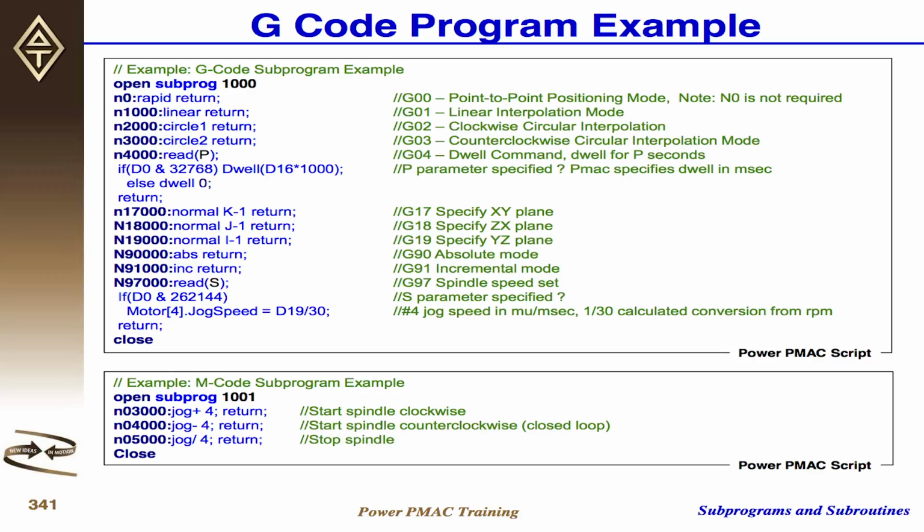So now you're checking the D0, this is the whole register, and the 2 to the 15 of the bit, which is 32,768, right? 2 to the 15. If you check this in the if statement, you're going to see if that bit is high or not. If the bit is high, you have successfully read it. So that's why you want to check this one.